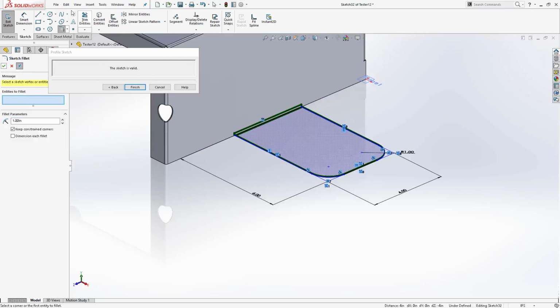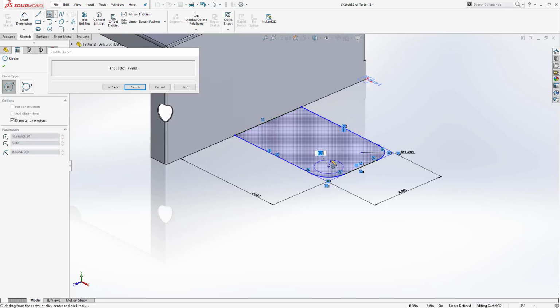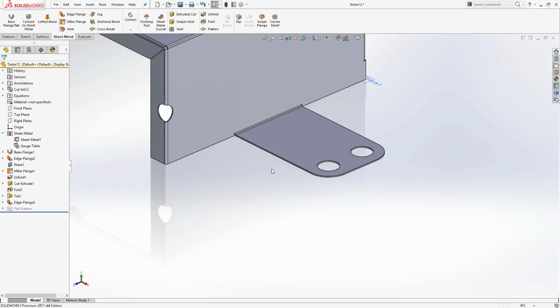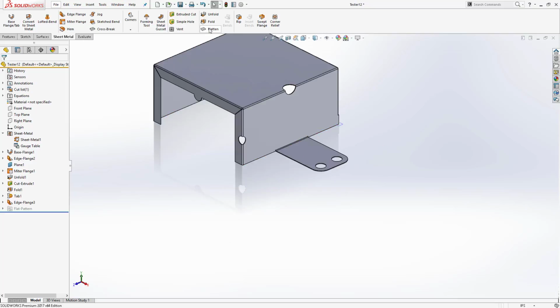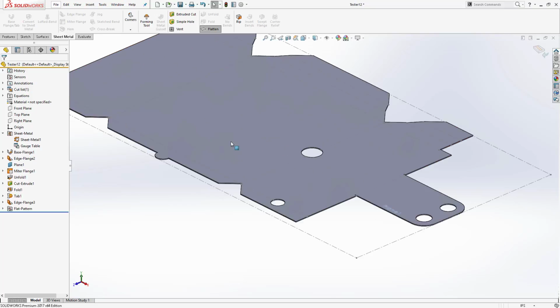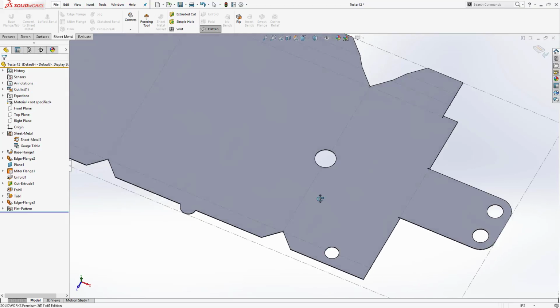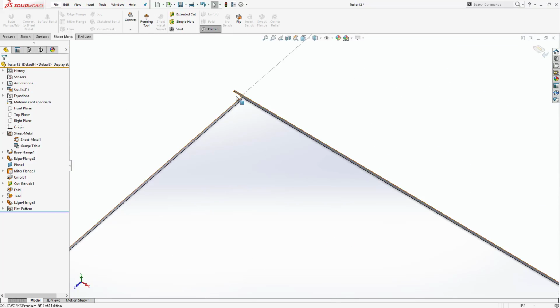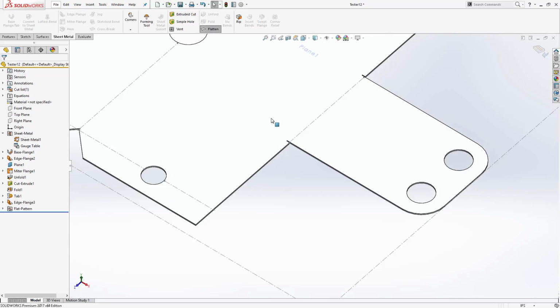And then another cool thing is you can actually add cuts into this at the same time. So if I want maybe 2 holes going at each of these radii, I can go ahead and click OK. When I hit finish, I'm going to get this fully new flange pulled out. It's got my cuts in there. Everything's already applied. Go ahead and look at my flat. Boom, that thing's working. So pretty cool way to just add things in there without having to have a full flange profile and then cut it out and then add some other things in there. You're also going to notice it added those rectangular cuts that we were talking about earlier. That's that auto relief working for you.